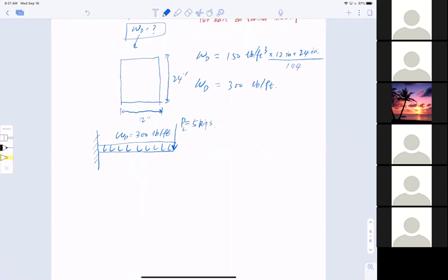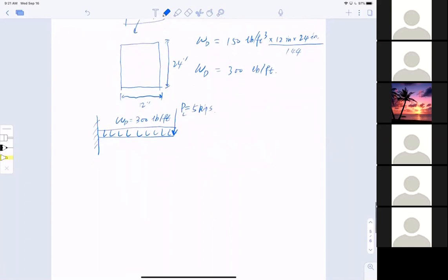Jack, Mr. Meadows. Yeah, I'm here. Hey, how are you doing, buddy? Good. Section A is at the fixed support, section B at the free end. Which section will be the critical section for my design, A or B? Section A. Exactly, so that is the critical section. Thank you. Now I want to sum the moment.